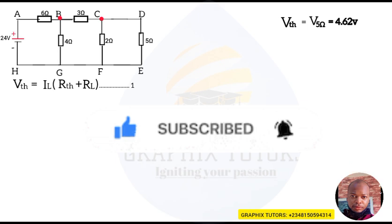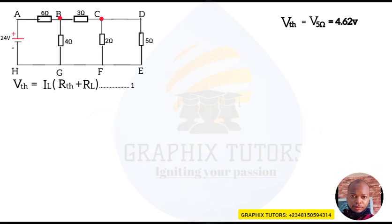Now we proceed. We've gotten our VTH now. The next step, if you look at our formula at equation 1, what's the next thing there? We'll go and look for our RTH first. Right? We'll look for what? Our RTH. So the RTH means the Thevenin resistance.